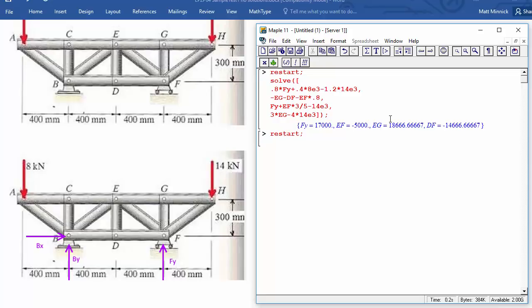Okay, so let's just go in alphabetical order there. At pin A, we've got a force in the x direction. What do we have? We have AE to the right, and we've got plus AB, the horizontal component, times 0.8. So that's the 4 horizontal over the 5 hypotenuse, and that's it for the x component. When we don't say equals 0, then that's implied for the solve command, which, by the way, I guess we should write. Okay, solve that thing, and that means that equals 0.